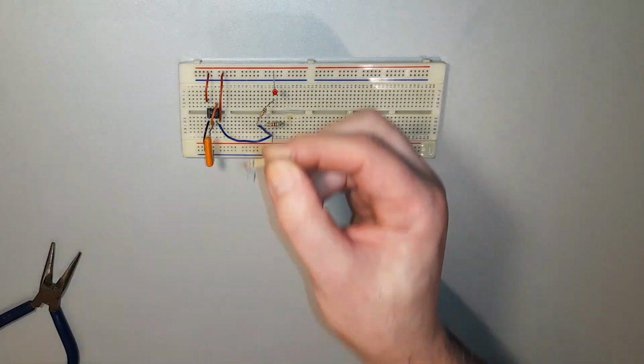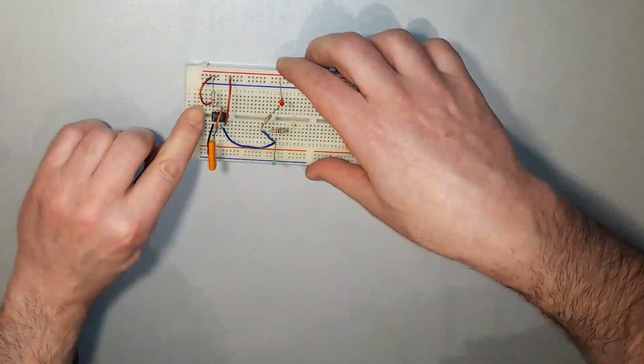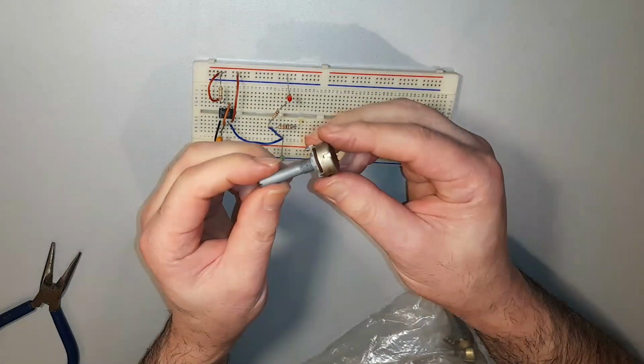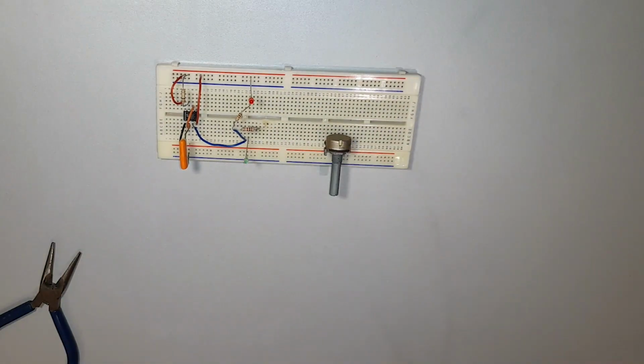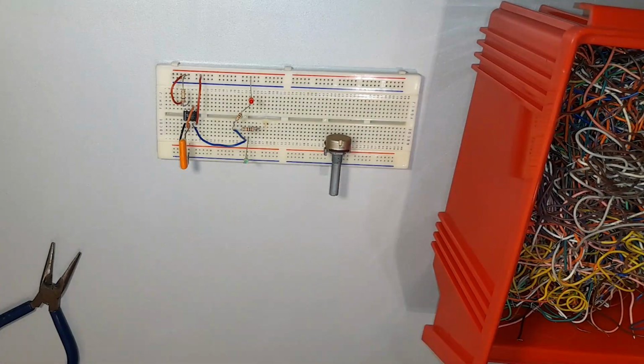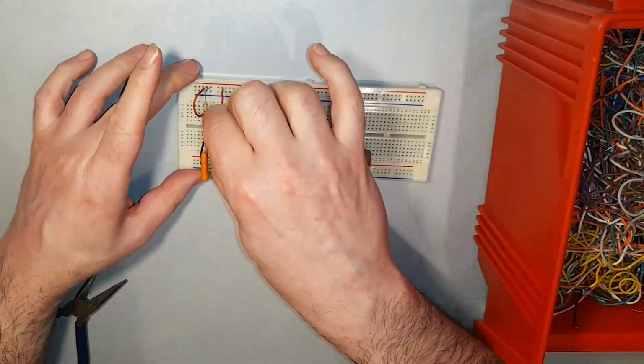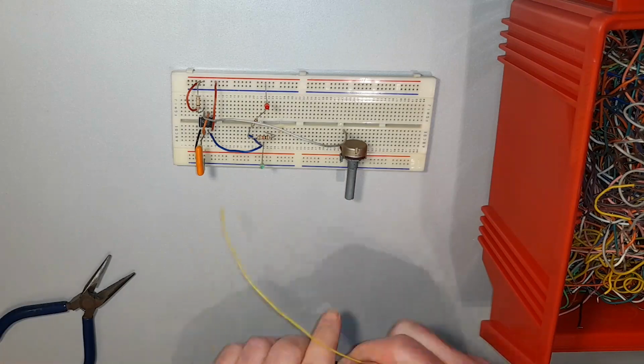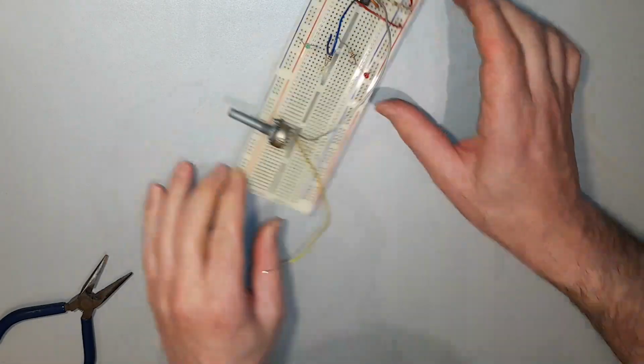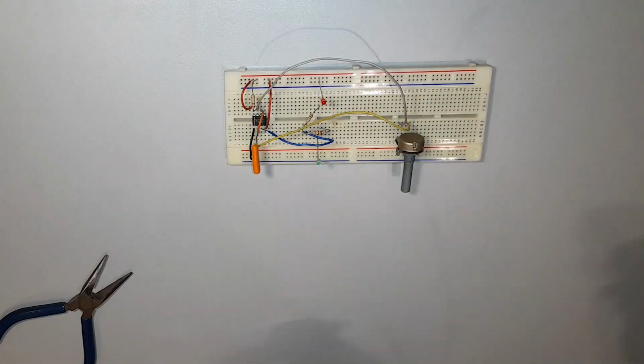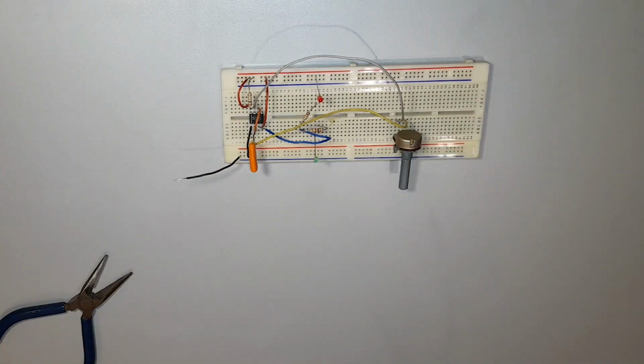Now I'm connecting a 100 kilo ohm resistor from positive to pin 7. Next I have plucked a convenient 5 kilo ohm potentiometer or variable resistor, which I'll connect between pins 7 and 2. Lastly, a couple of wires to connect power to the circuit, and our initial build is complete.